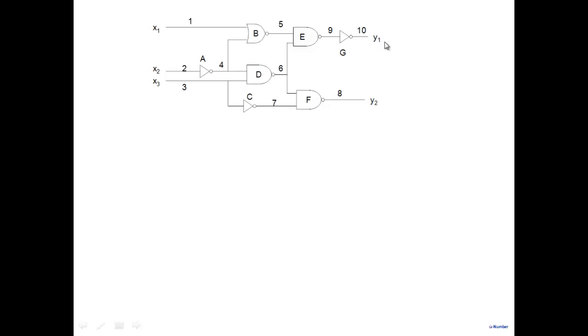Right? So what you would try to find out is, what is the worst case delay in my circuit, right? Which translates into, you want to find out the longest path in the circuit. The longest path could be, I don't know, this, maybe this, or this one, or whichever one. You want to find the longest path. And once you find the longest path, you add up the delays of each element on that particular path. So what you're trying to do is find the critical path. And then add up all the delays on the critical path and check whether the delay is less than your constraint or not. If it's less, then it's fine, it's okay. How do you find the critical path?